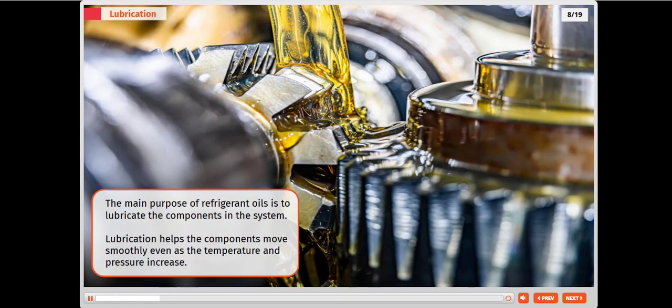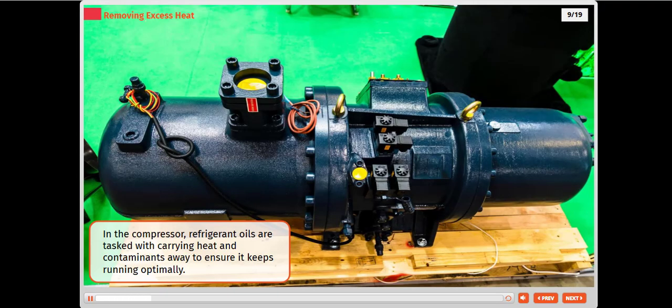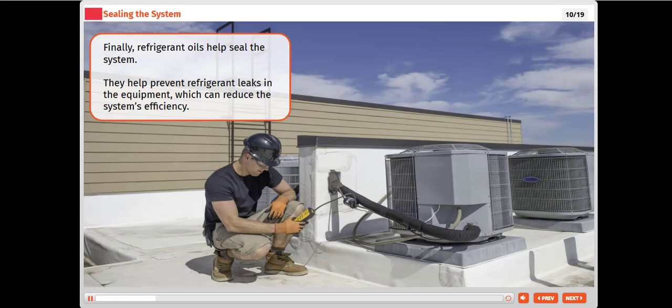The main purpose of refrigerant oils is to lubricate the components in the system. Lubrication helps the components move smoothly even as the temperature and pressure increase. In the compressor, refrigerant oils are also tasked with carrying heat and contaminants away to ensure it keeps running optimally. Finally, refrigerant oils help seal the system. They help prevent refrigerant leaks in the equipment, which can reduce the system's efficiency.